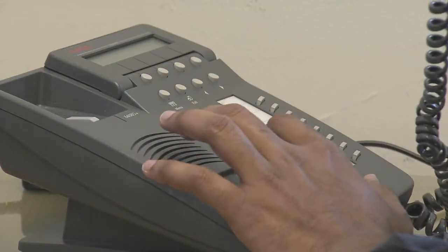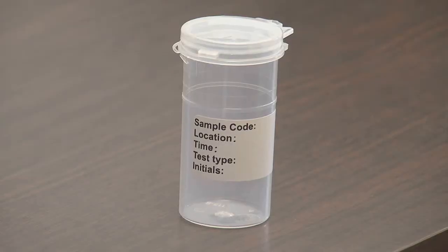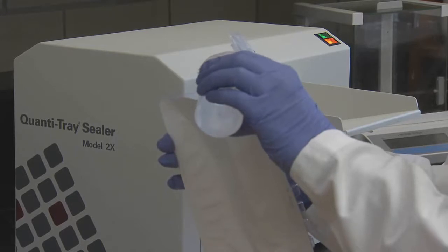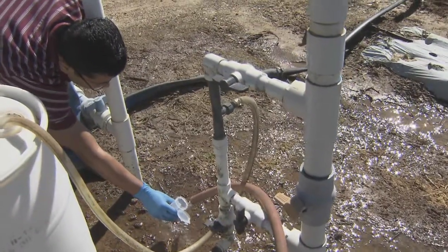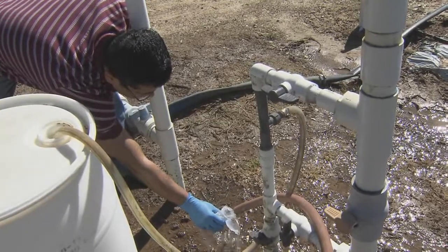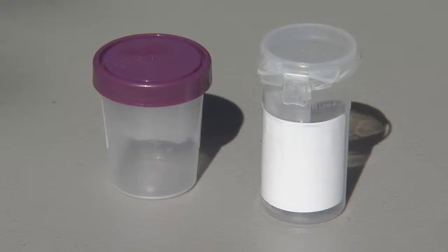The first step should be to contact the lab performing the analysis to determine if a special specimen cup or bottle provided by the lab is needed. Make sure both parties understand and know what type of microbial testing is needed and what the general requirements are for collecting a water sample. Only sterile sampling containers should be used. Most labs provide a 100 milliliter container with a snap lid or a screw cap lid.